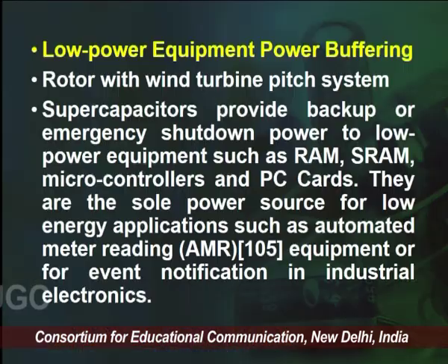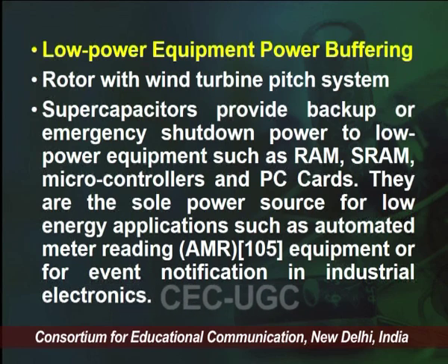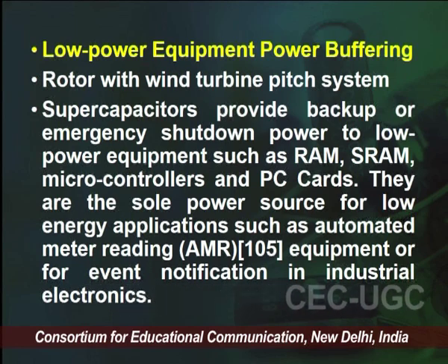To overcome this problem, supercapacitors can be implemented as an interface between the load and the grid, to act as a buffer between the grid and the high pulse power drawn from the charging station. Another important application is low power equipment power buffering, like the rotor of a wind turbine pitch system.